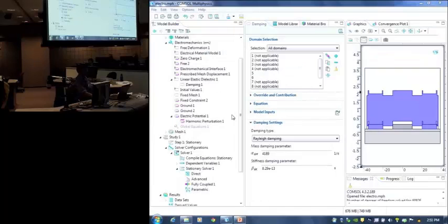Usually, how do you get these values? Well, it's not that easy. Usually you have to find out the critical damping ratio, which is available in literature for two particular frequencies. Knowing the critical damping ratio and knowing the two frequencies, you can back calculate the values of these parameters, alpha and beta. Usually you don't get directly in literature that here is alpha, here is beta. You'll have to calculate those parameters.